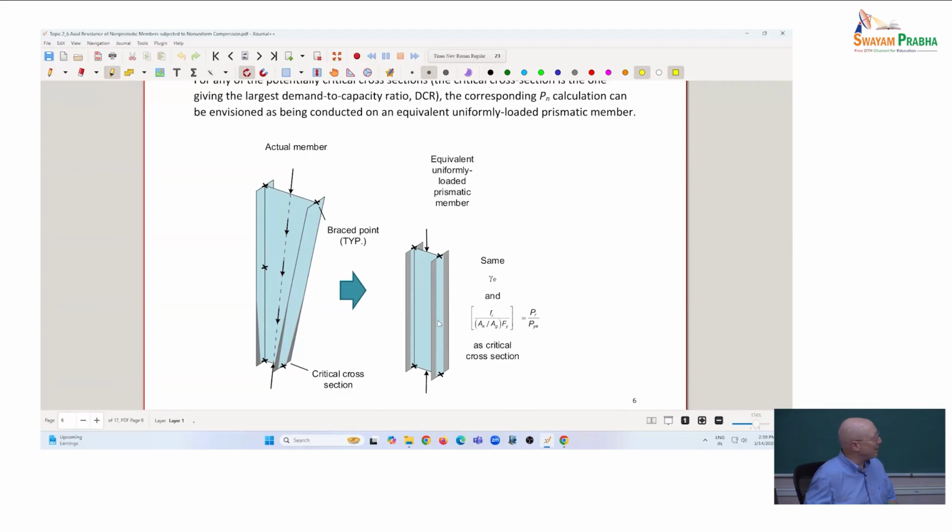So here's where you might have questions of, oh, really? But gosh, the tapered member, we've got stresses that are varying quite significantly on the length. Isn't it very conservative to just use something that's based on uniform along the entire length? Take my word for it or check it out. You'll find that the calculation is generally pretty good.